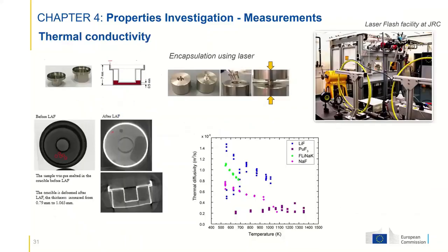That was the one before last, and the very last is thermal conductivity. Thermal conductivity is measured by the laser flash technique. Normally we use this technique to measure solid oxide pellets, in a semi-hot cell, so we also use it as part of PIE to examine irradiated oxide fuel pellets. We put the pellet at the temperature at which we want to determine the thermal diffusivity, shoot a short-pulse laser on one side, and measure the temperature response with respect to time with pyrometers. That is proportional to thermal diffusivity, provided you know the porosity, and if you know heat capacity and density, you can get thermal conductivity.